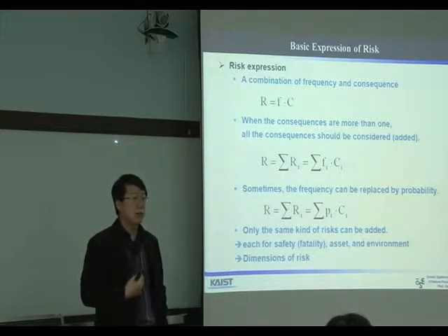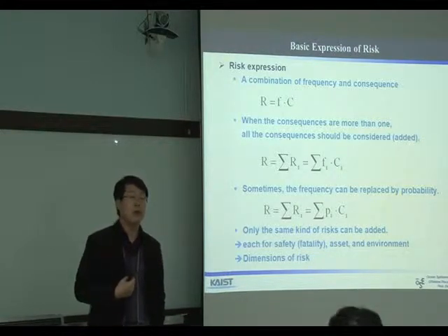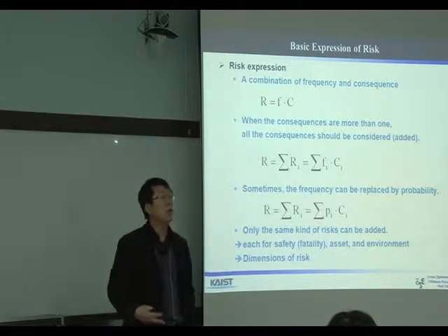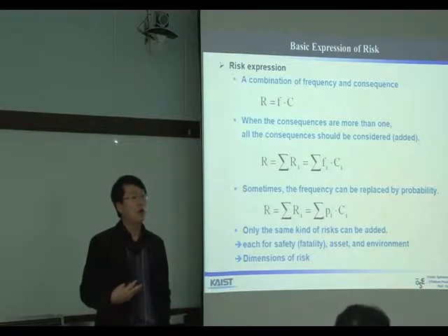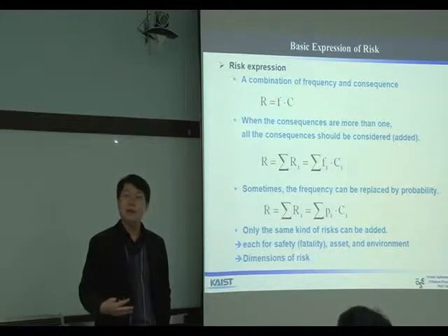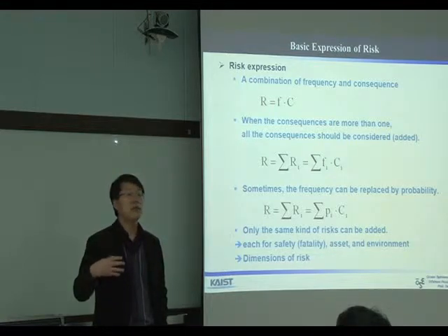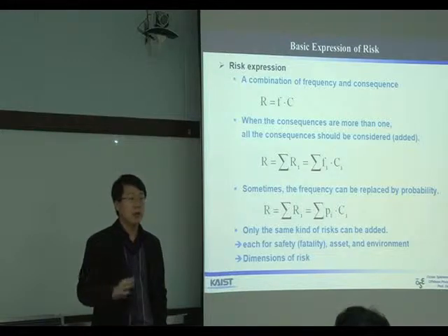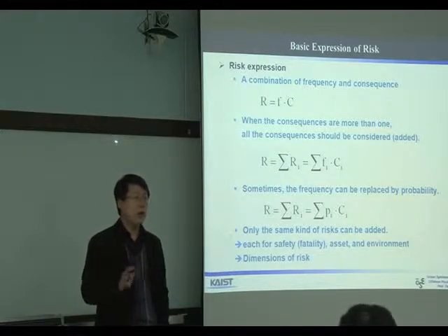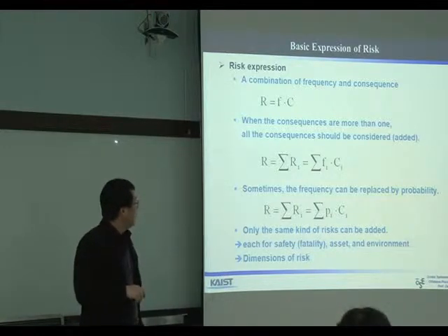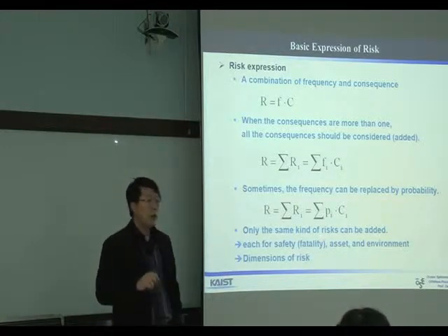For example, PFD, probability of failure on demand, is defined in terms of probability for the low demand case, and for the high demand case, it is defined by frequency. So you should be very careful in estimating the risk, and only the same kind of risk can be added.